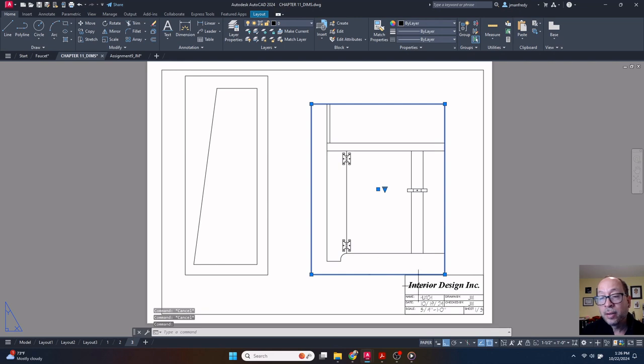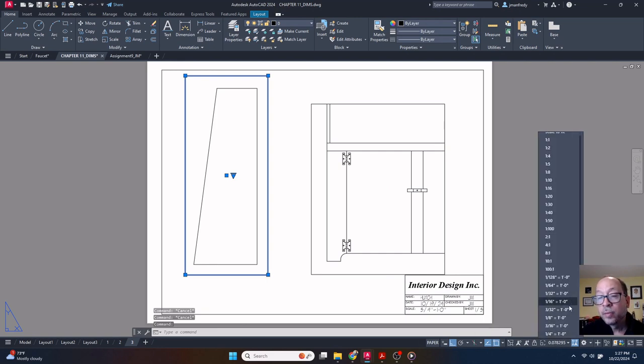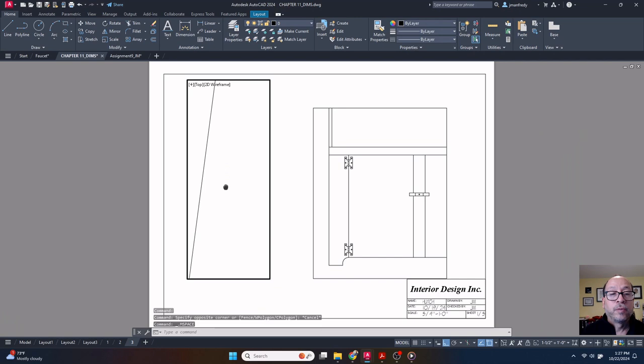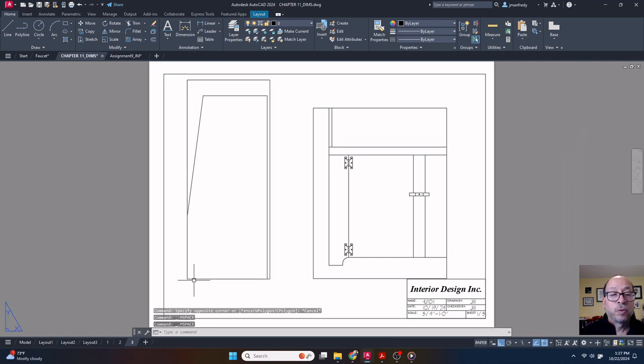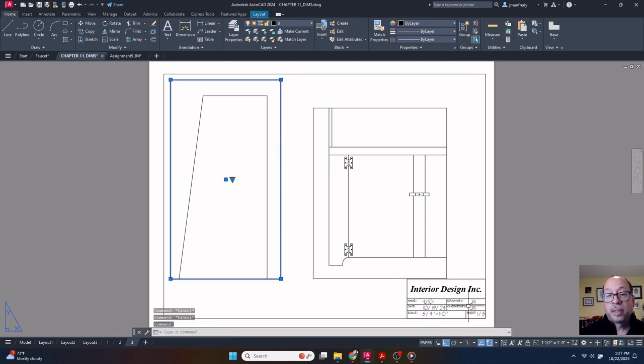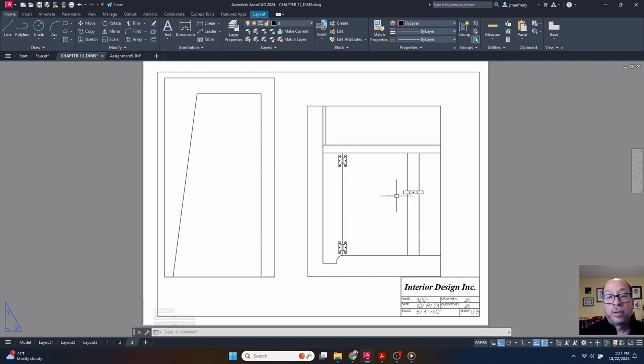This is set up for a 1.5 inch scale, and now I can put a padlock on it. This one here is set up at a 1.5 inch scale also. But it's only meant to focus on the very topmost piece here, the topmost portion right there. Again, you'll draw more accurately than I did. But once you have it at the scale you're after, click and lock that scene. So the design will show up here. This shows up here on the right. Then you simply put notes and dimensions.